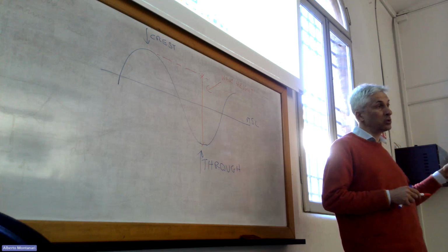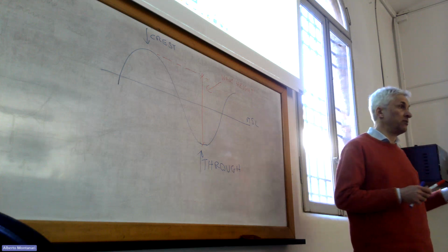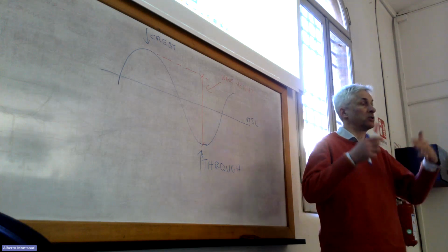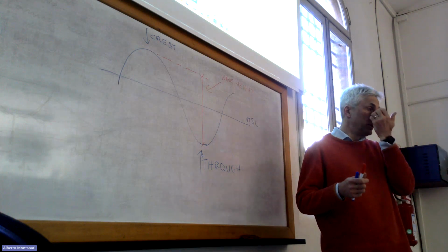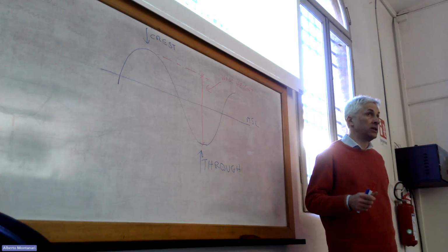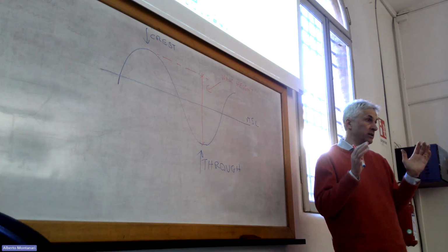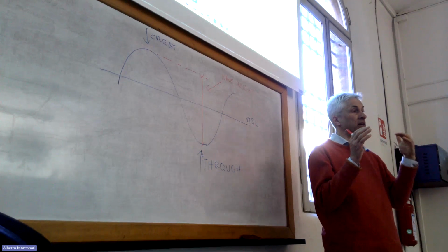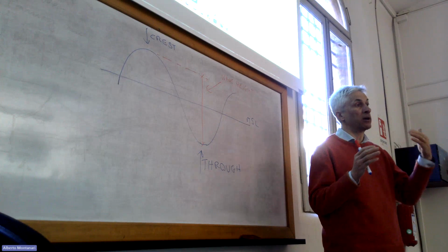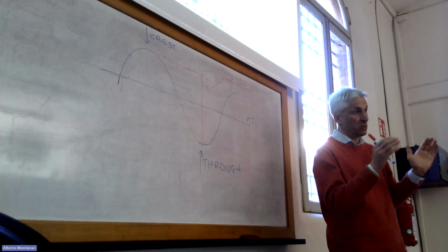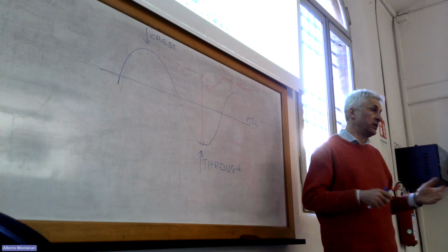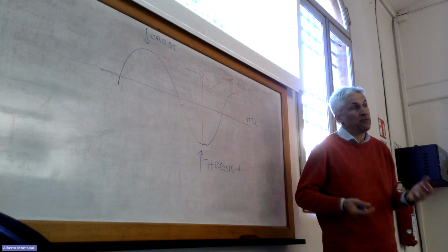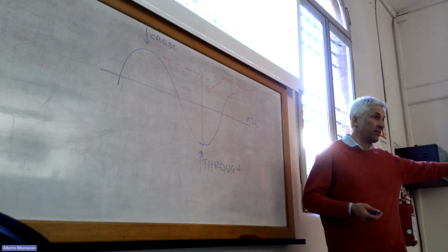Usually it's not a continuous measurement. So you are not given a continuous recording, meaning every 1 minute, every 30 seconds. Usually you are given what is called a block maxima, where block is intended as a time span. So when I say weekly maxima, it's a type of block maxima, where the block is the week. Usually we refer to monthly block maxima, which give you the wave height in each month.